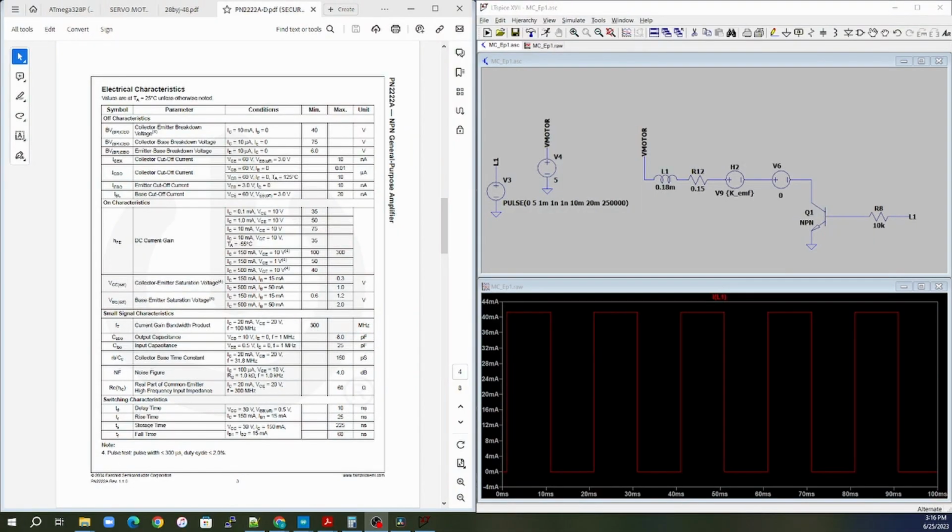So from my other videos, when I was talking about FETs and motor controls, I was using NMOSs to control the power on and power off, and I had an H-bridge to control bidirectional control. But for this example on the brush motor, I'm just simplifying it, and I'm only going to run the motor in one direction, so I only need one FET to control this. And you can also see through the schematic that I'm not using a FET here, mainly because I don't have a FET. I have a transistor, so I'm using an NPN transistor rather than an NMOS. Specifically, I'm using the 2N2222 transistor.